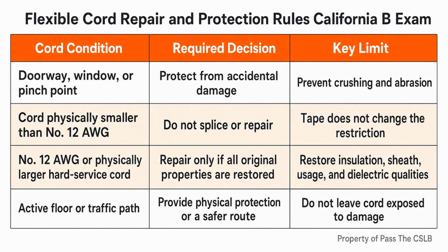The site safety program needs the same level of specificity. Under the Injury and Illness Prevention Program framework, the employer's written code of safe practices must relate to the actual operations and hazards of the site. A generic manual that never addresses the work being performed is not made effective by sitting in the trailer. For temporary power, site-specific practice may address who inspects cords, how damaged equipment is removed from use, which protection method is being used for temporary receptacles, how wet location boxes are maintained, who controls lockout, and how clear electrical workspaces are enforced. I am not inventing a universal form. I am showing the kind of operational connection the written practice must have to the real job.